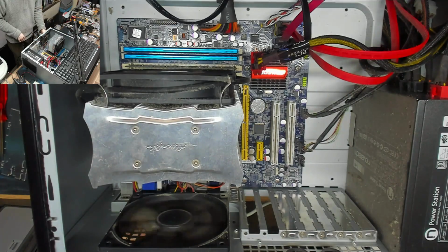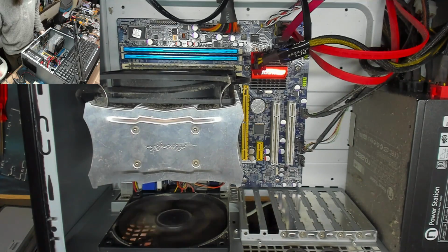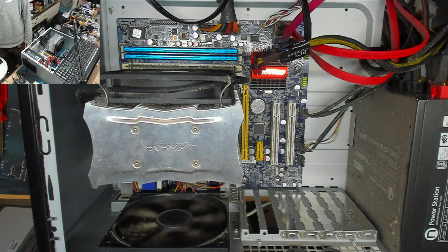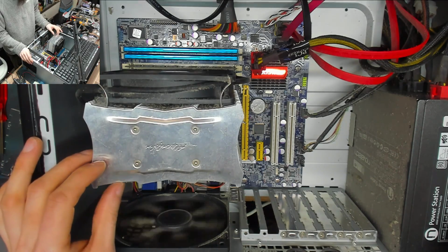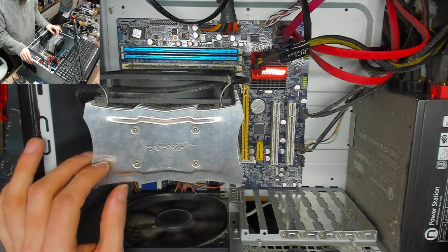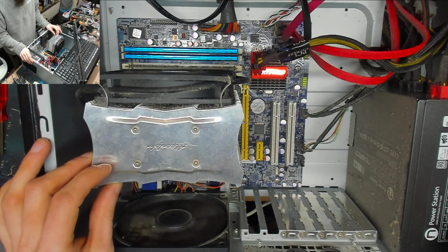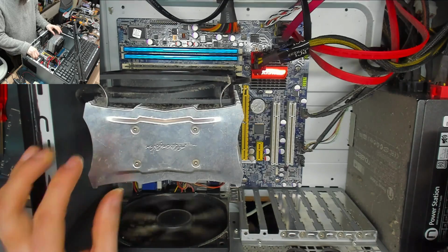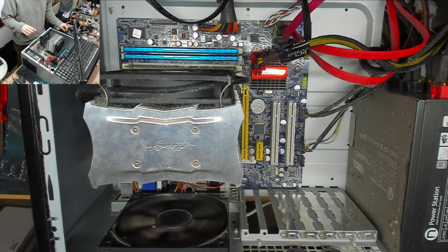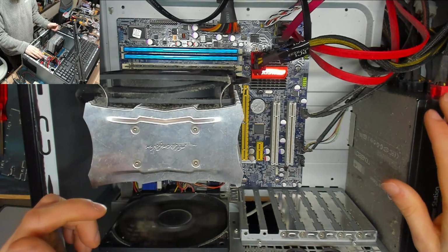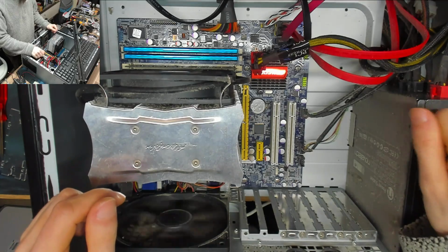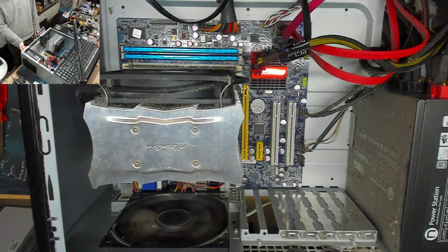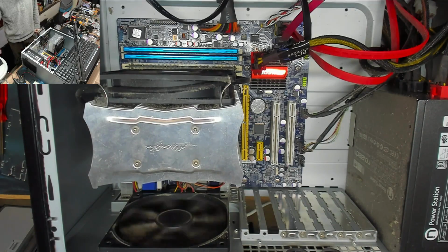No, we've got no VGA output now either, and it was giving us VGA output before. Well, it looks like we're back to square zero with this. So, okay, I think what we're going to do next is I'm going to plug in a different power supply, and we're going to try that because I have big concerns about this power supply. I think this power supply is cooked. So let's get the Antec.